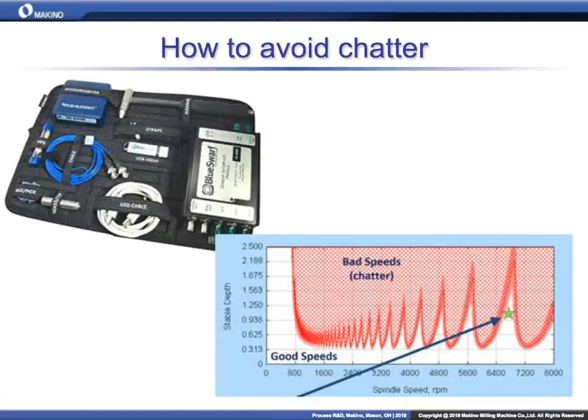And when we're trying to figure out what the tool's natural frequencies are, this method lets us excite the tool, or hit it. And that's an instrumented hammer, so it measures the force with which we excited or hit the tool. Yeah. And we're not talking about destructive hitting. These are taps. You're just giving a little knock. Correct.